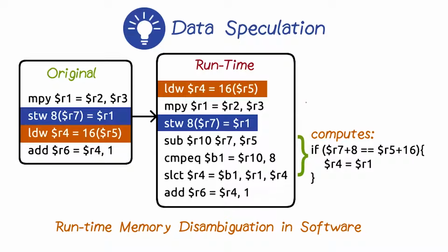Let us understand how we can do some of this data speculation, disambiguation through a series of instructions in software. Earlier I mentioned to you a hardware mechanism of just simply re-executing the load, but of course it does cost additional mechanisms to be implemented in hardware, and embedded systems may not have a provision for such correction. So an alternative is given many times to an embedded system designer to put some software instructions and the memory disambiguation to be implemented via software route.